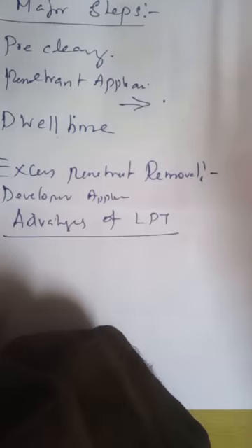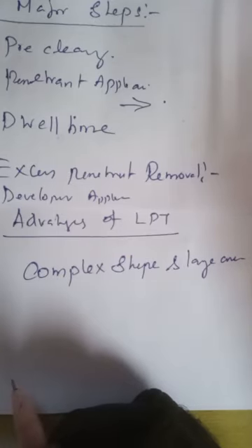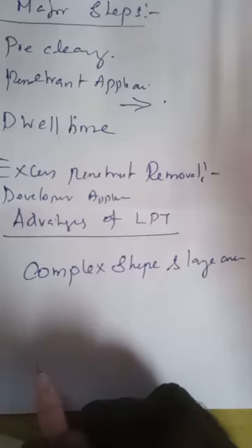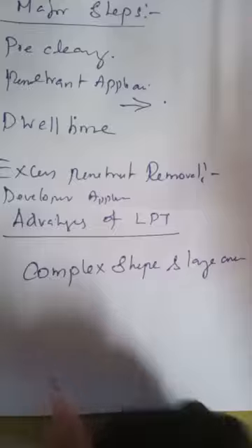Advantages: works on complex shapes and large areas, portable and inexpensive, sensitive to very small defects. Limitations: surface breaking defects only, cannot find internal flaws. Not suitable for porous material.